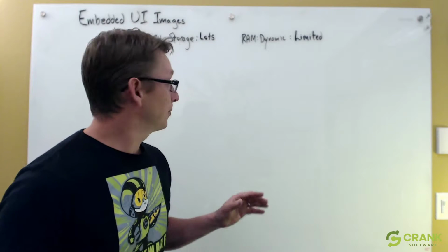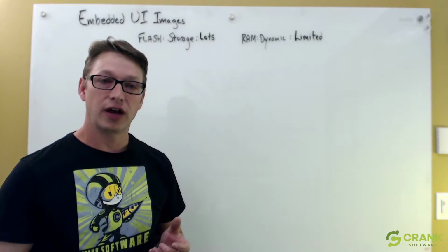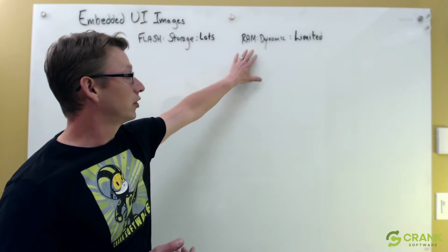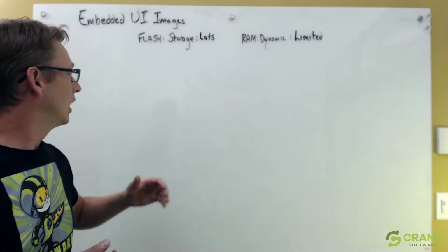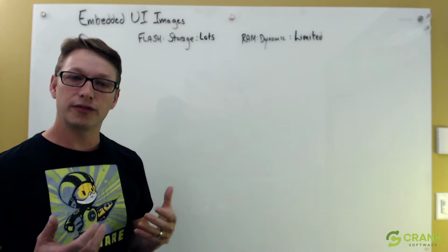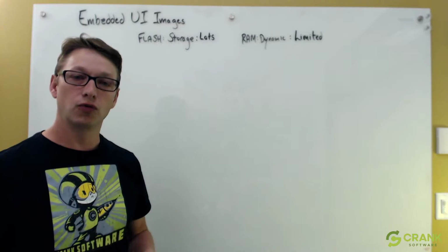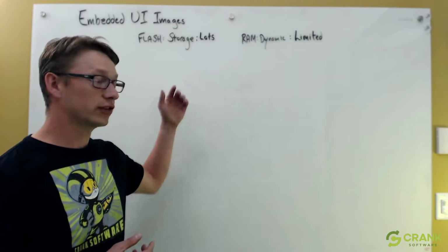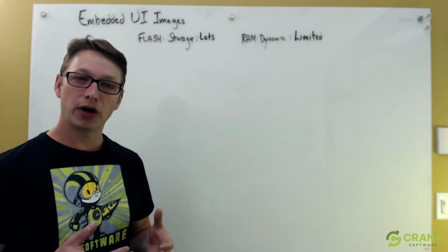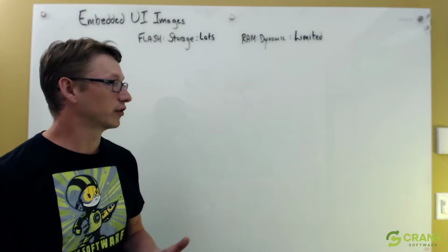So let's recap a little where we were last time. We were talking about two different types of memory configurations, different types of memory use: flash memory, and RAM, dynamic memory. Flash is usually a very abundant memory, with a lot available on the system, but because of its access characteristics, it really favors reading content off of it. As a result, it's used a lot for storage, for your code and the data of the program, but not a lot for writing content. It can be used as a persistent store, but its access time is very slow for writing.